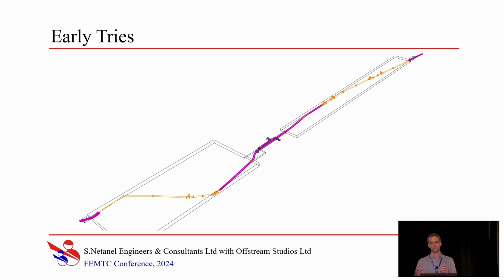But then, when flow was becoming substantial through the boundaries, I got access violations, like a lot. Now, the way that I understand it, an access violation means that the simulation is trying to access RAM that wasn't allocated to it. You can try to restart those simulations. It's not going to work. All you can do is check your setup, start from scratch. Tried a lot of things to solve that.